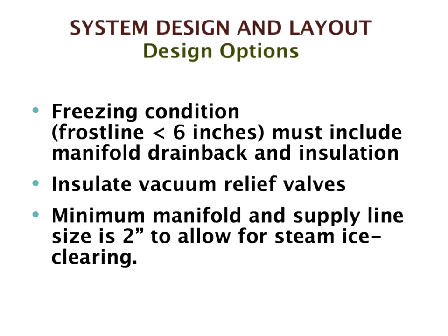Your vacuum relief valves are one of the first things to freeze. They must be insulated if you're at risk for freezing. If you're in really severe freezing conditions, keep your minimum manifold and supply line size to 2 inches, so you can use a steam ice clearing device.